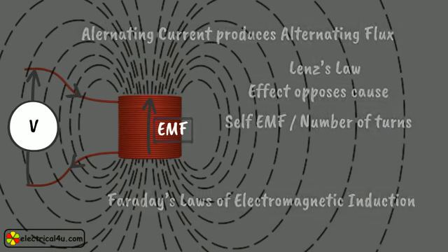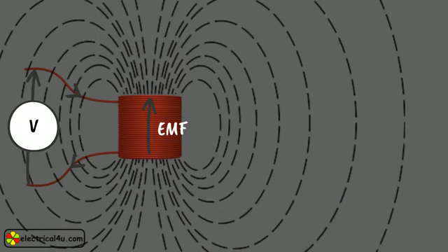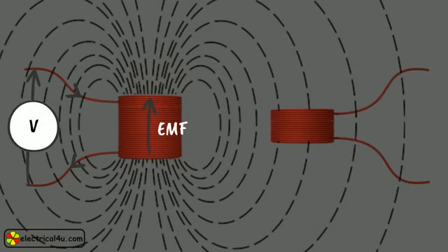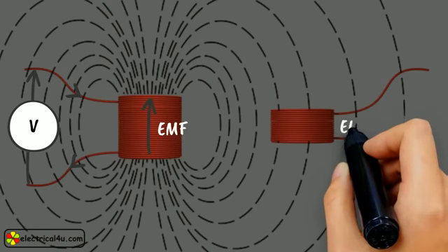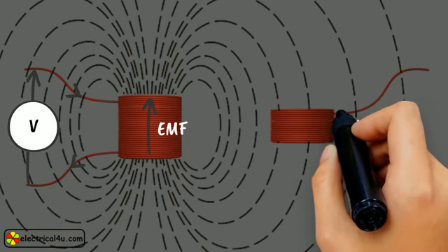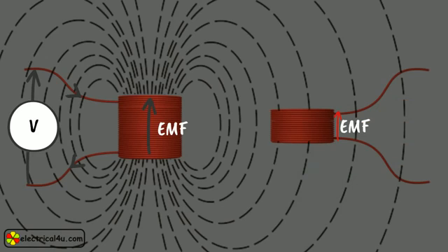We have said that there is another winding in the most basic transformer, but till now we have not discussed it. Now we are coming to second winding in the transformer. Supposing one separate winding is brought nearer to the first winding, then this second winding gets linked with a portion of varying flux of first winding. Due to this varying flux linkage, there will also be an induced EMF across it. This induced EMF would be quite small, as the flux linkage is small.